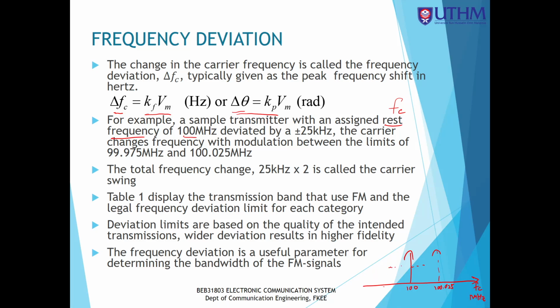The carrier changes to 100 mega minus 25k, so 99.975 megahertz. This is delta f, and this is also delta f.